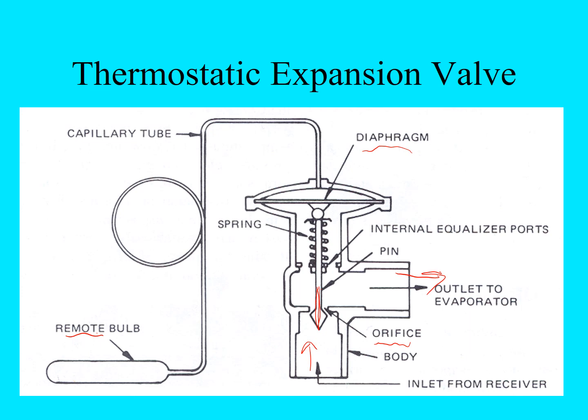So as the refrigerant on the outlet changes its temperature, the orifice can change up and down to increase the refrigerant flow into the evaporator or decrease the refrigerant flow into the evaporator to make sure that all the refrigerant is going to vaporize when it leaves the evaporator core so that it can get back to the compressor as a low temperature, low pressure vapor.